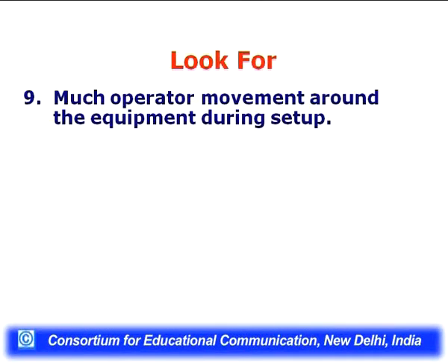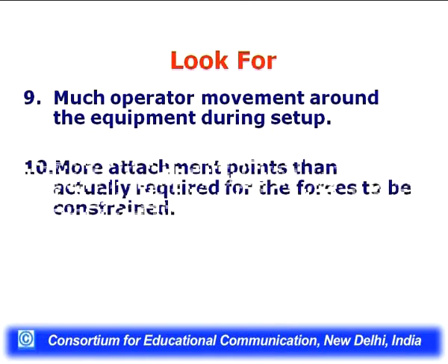And look for much operator movement around the equipment during setup. We have to look for the area where more operator movement is there in the existing method. We have to pick up those points and we have to reduce the operator movement. If we are able to reduce the operator movement, then changeover time will get reduced, setup time will get reduced, and our SMED will be very effective.